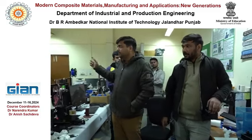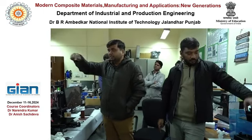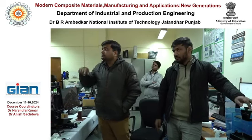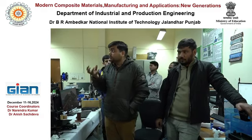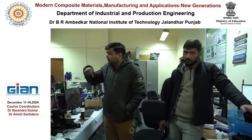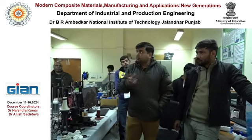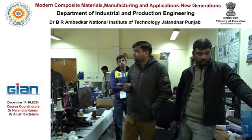But in FDM, what we were doing, we were making the whole layer by depositing the material in the form of patterns. Similarly, in SLA, stereolithography, we have a laser-based energy source, UV light. So it scans the whole layer by moving along X and Y direction. But here we have a projector, so that is switched on, right? So at a time, a single layer is formed.